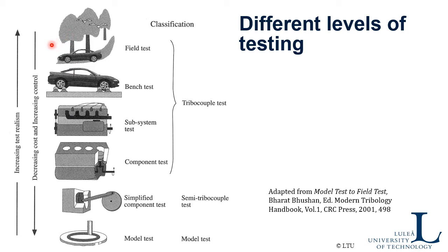The cost goes down in this direction, and you also have more control of the conditions in the contact. On the other hand, you may not be able to mimic all the real conditions as you have in the field test in this tribotest. But the success factor here is of course to understand the model test, to understand how the model test links to the field test as well as possible. And that's a trick you have to learn over many years of experience of being a tribologist.